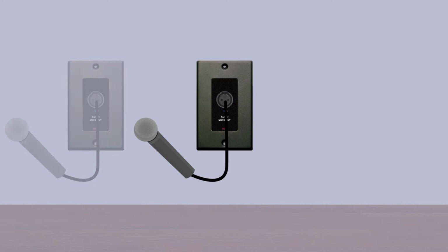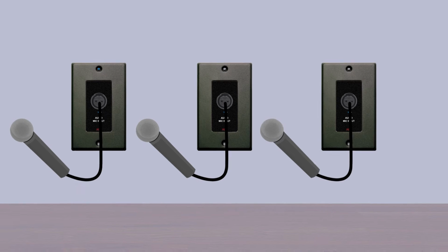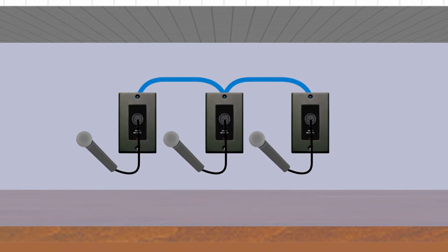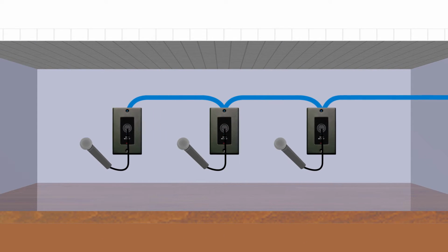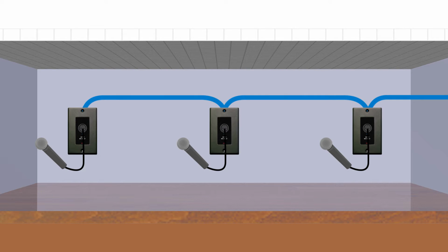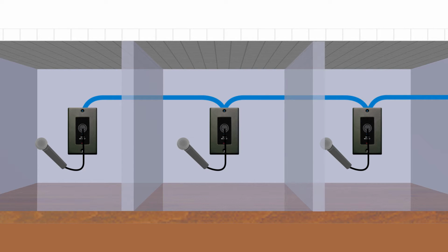Audio sources connect to Format A senders. Up to 3 single-pair senders can feed a single twisted pair cable run. The senders do not need to be located together. In fact, each sender may be in a different location or even in a different room. They are connected along the cable run in series from one to the next using standard RJ45 connectors.